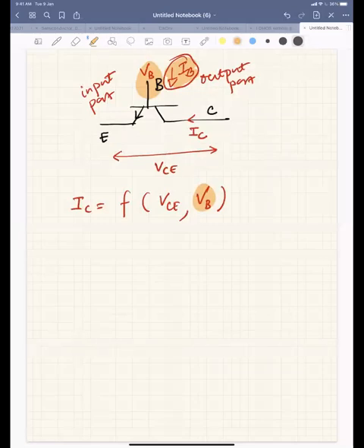So these are the two conditions when we are designing an active device. When I talk about designing an active device, it's not about doing some circuit design. It is about designing the device itself. How do you design the device? From the outside, it looks like I have an E, B, C, but when you go inside the device, as we have also seen in the PN junction, how do you design that device so that your base current, in this case your control current in the control terminal, is very low, and your IC, your collector current, is equal to the emitter current?